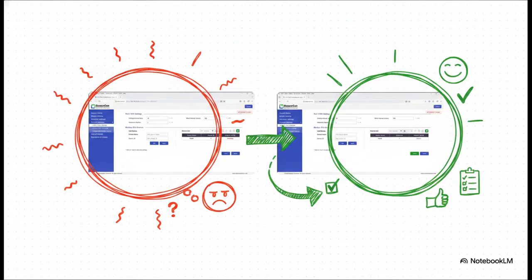Now, check out the visual feedback in the device list table. When you first add EM01, the register config status shows up as a red pending. This is basically the system's way of saying, hey, I see the device, but I have no idea what data to pull yet. It's going to flip to a green done only after we've successfully built our groups. It's kind of like a fantastic built-in checklist.